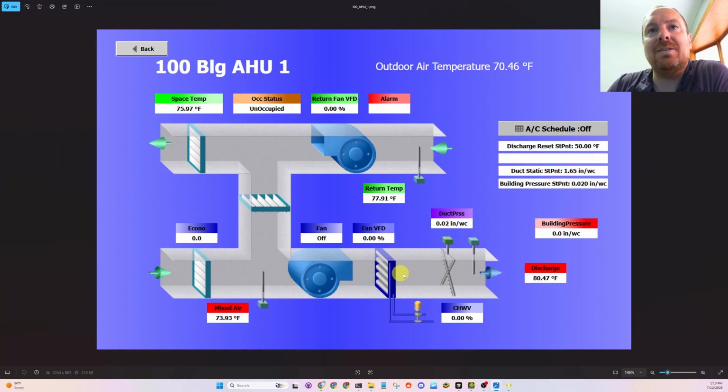This fan needs to have a certain amount of static pressure in it by design to push air all the way where it needs to go down the duct stream. When that degrades over time from some faulty part somewhere in the mechanical system, they'll compensate. They'll just lower the whole thing, make everything colder in the whole air handling unit, which may work as a band-aid, but it'll cause excess reheat. Everything else that doesn't need that extra cooling will be having to reheat.